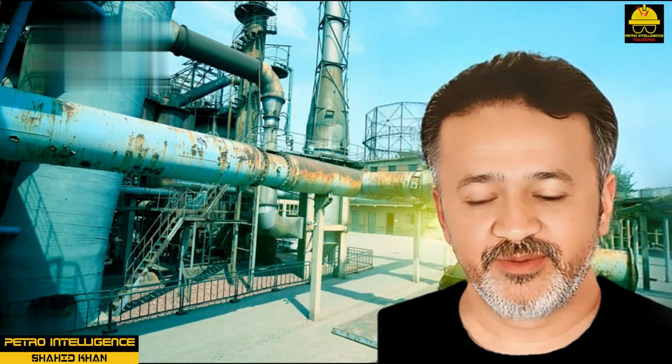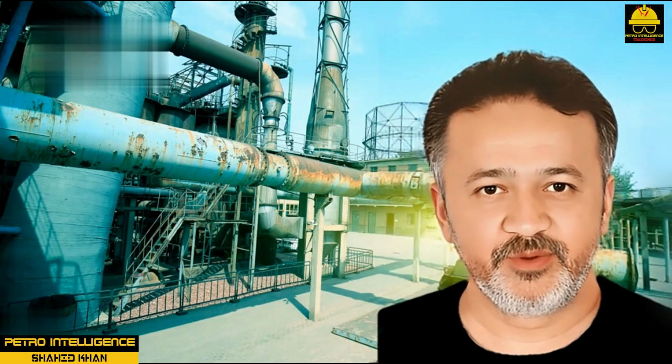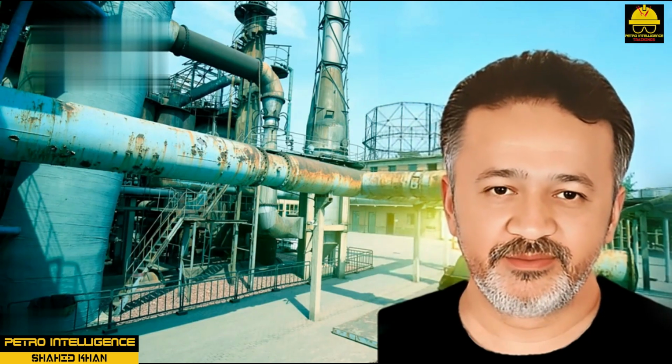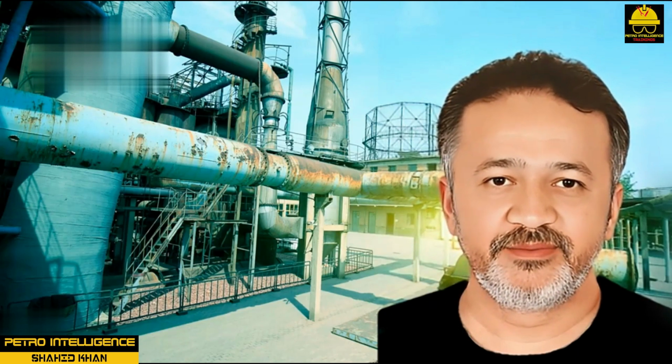As boiler feed water temperature increases, impurities precipitate, fall out, and adhere to the hot metal surfaces of the boiler, forming scale. Typically, dissolved bicarbonates of calcium and magnesium break down and form insoluble carbonates. Deposits in a boiler are composed of a variety of compounds, including calcium carbonate, calcium phosphate, sulfate or silicate, magnesium hydroxide, iron, copper oxides, and silica.